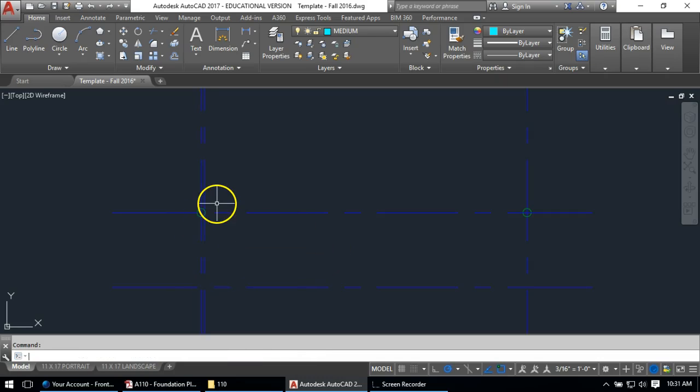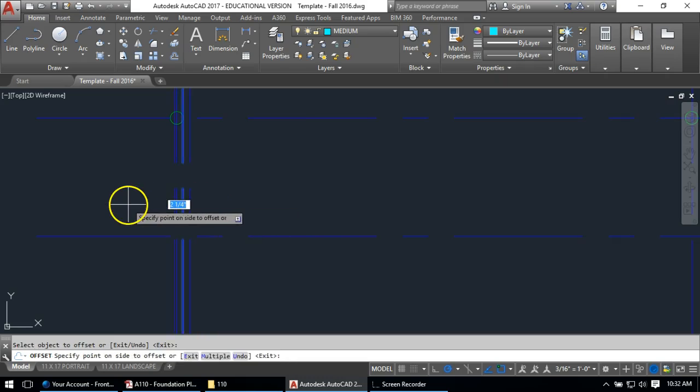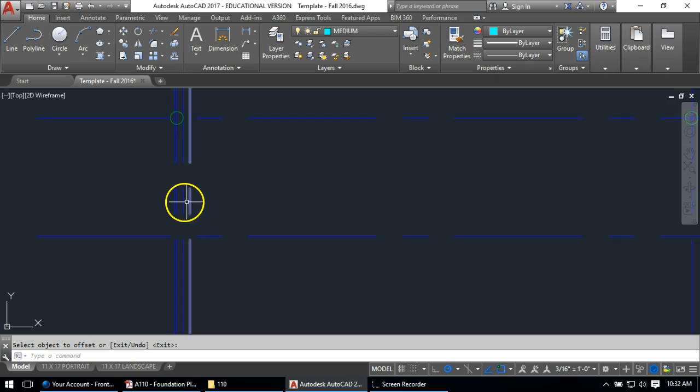That's the center point of my railing. This line that I just drew here. Now the railing itself is 4.5 inches, so that's 2 1/4 inches on either side of that. So I'm going to offset again, offset 2.25, enter. Oops, what did I do? I think I missed my offset button or something. So offset 2.25, enter. To either side of this line, there and there, is my railing.